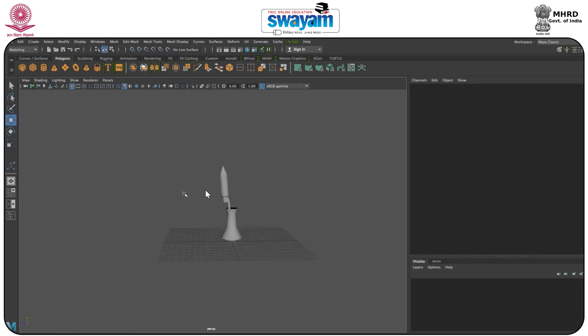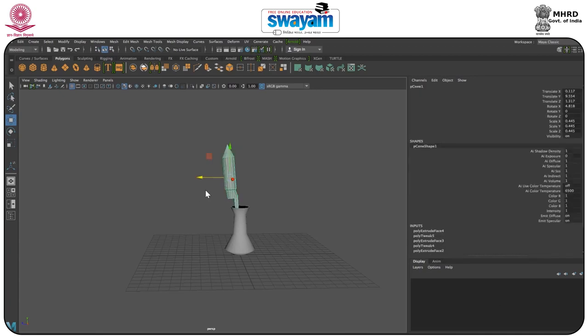And what happens now will be in 120 frames, so we'll just rename this 120 because we don't require 200 frames. Now we'll start animating. Before animating, make sure that this button is checked, because this is the auto key, so you don't have to press S on the timeline all the time. At first you just put S one time, to lock its position.